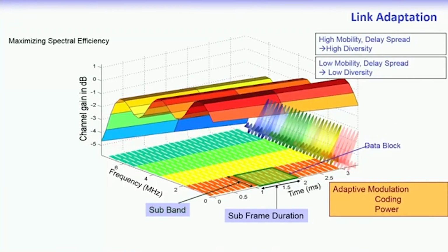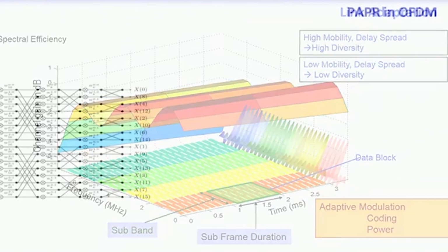This particular picture is also important in terms of the time-frequency diagram, because whenever we are talking about the frame structure, the frame design or any other thing, this picture should be available in mind. There is a time, there is a frequency, there is a group of symbols, and as we have always said, this is the time duration, the OFDM symbol duration, this particular part. This is the subcarrier bandwidth. So, the entire picture should be available in mind when we are discussing such things.